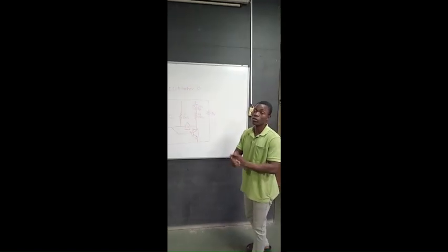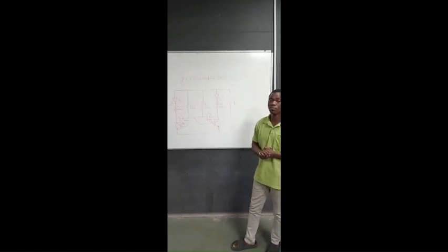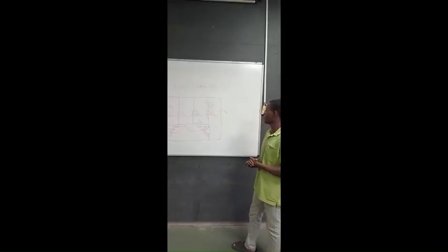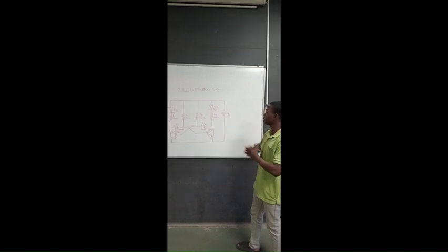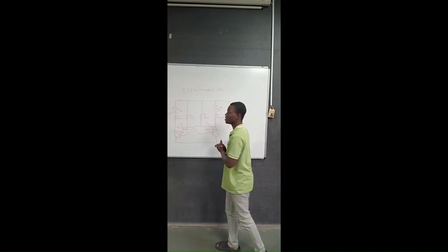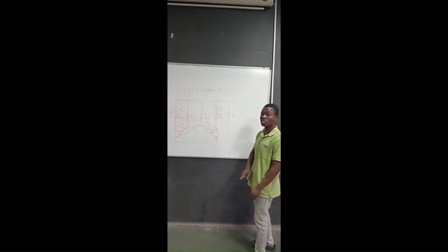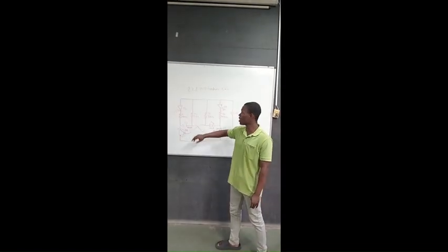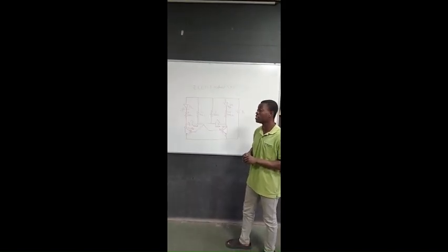So now I'm going to explain in brief how our circuit works. When we connect the power supply in our circuit, we have 9 volts. There's going to be a slight difference in our components that is going to cause one bipolar junction transistor to turn on, allowing current. If this one turns on, it allows current to pass through to the corresponding light emitting diode.